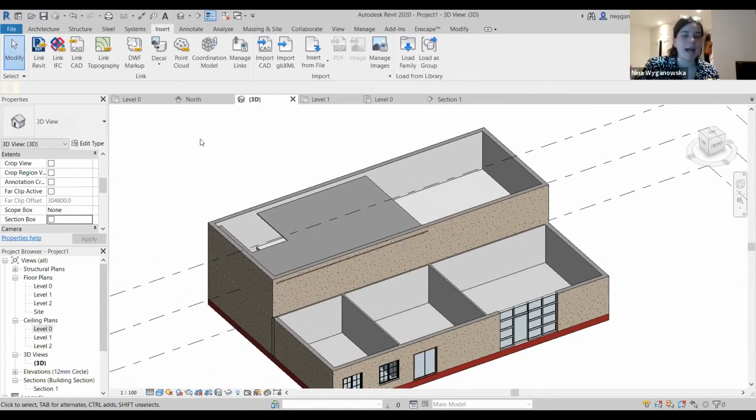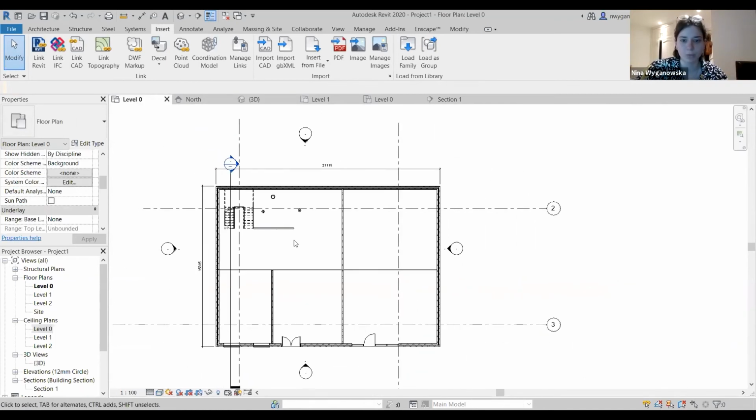If you upload your plans, always separate your plans. That's a tip. Always separate every single floor plan into different CAD files. So if your level 0 is level 0, just have a level 0 plan, then a level 1 plan, then a level 2 plan. And then you upload them to the exact level you want, because all of them will upload at 0,0 automatically onto your plan, and it will all overlap, and they're unmovable from there.